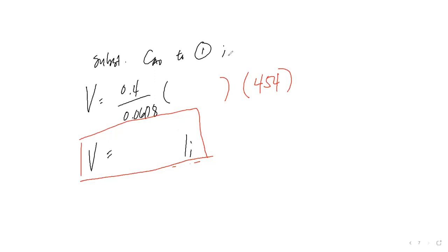6,620. Almost the same. So we will use the 6,620. I think it's in the decimal, 6,620. Okay? Or you can have 6,619.32. But more or less, this is the volume in liters. Quite big. 6,620 liters. That's the volume of our PFR.